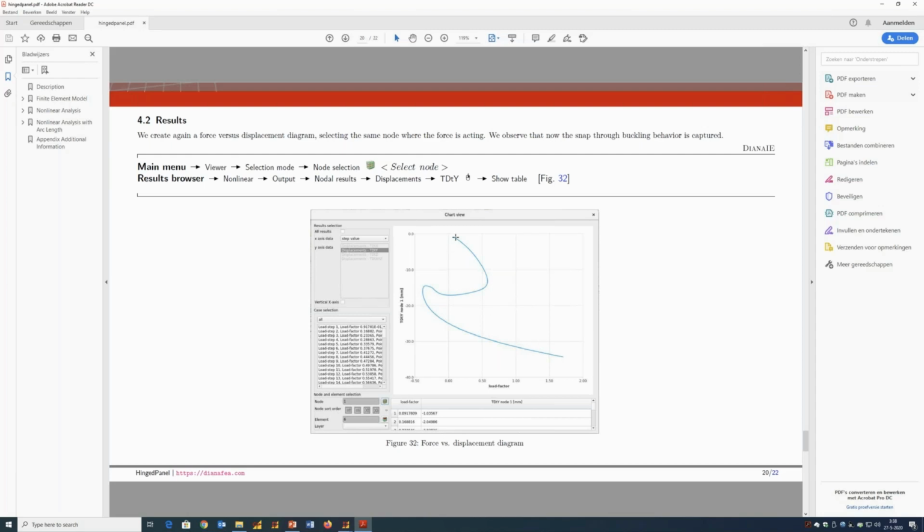So this is one of the powerful tools that you can use when you have to capture such a behavior, is to activate the arc length method. So this is it for the presentation of today regarding this nonlinear iterative procedure and tools. What we learn is that a nonlinear analysis is more complex than a linear one, of course. You have more settings to take into account, but always try to keep things simple and don't activate all the exotic features that Diana may offer in one go.